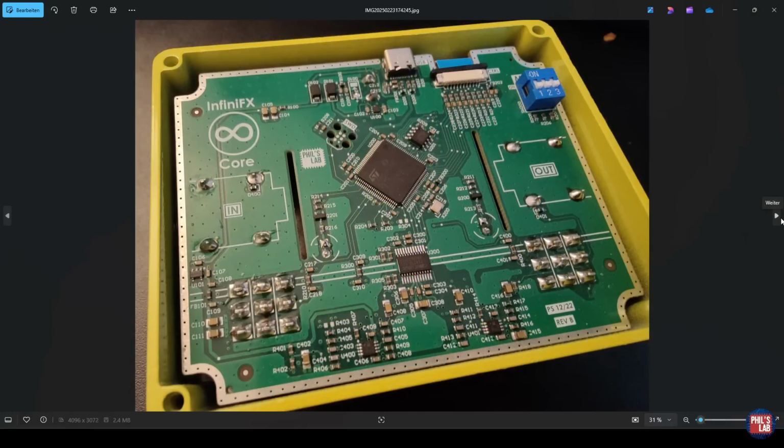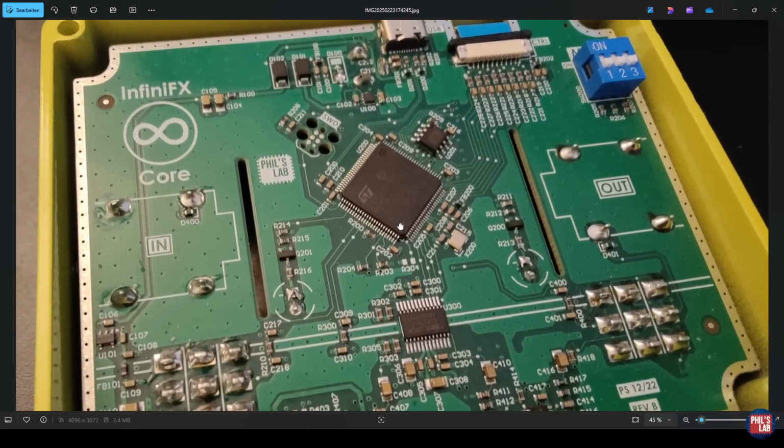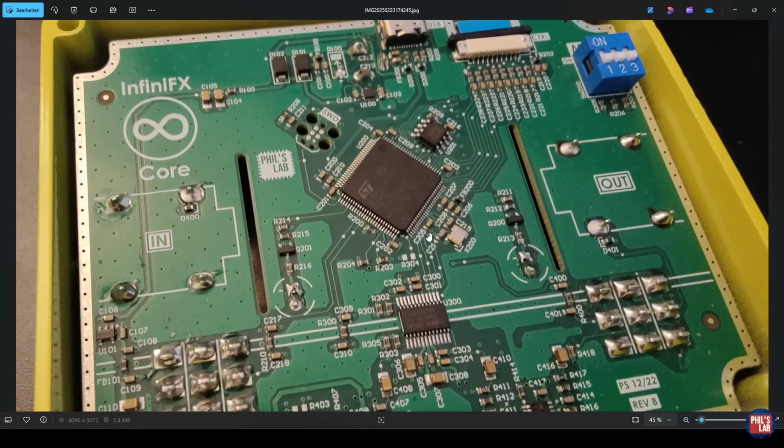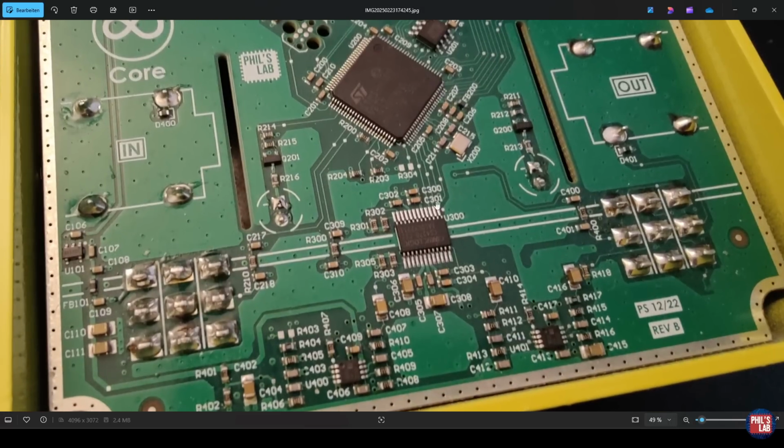Flipping this guitar pedal over, we can actually see the core of this pedal, which is a main DSP PCB and actually a control PCB with the potentiometers below to make sure the mechanics work out. This particular PCB contains an STM32, which is a pretty beefy microcontroller which we're using for all of our digital signal processing. This interfaces to a Cirrus Logic codec via I2S, which in this case for this pedal I'm just using a single mono input and a single mono output, and all of these analog filter sections are tailored for guitar.